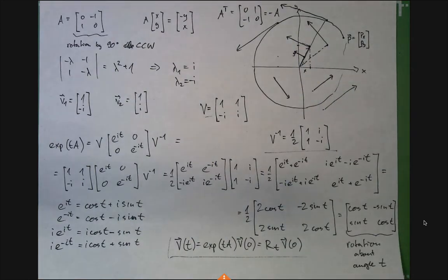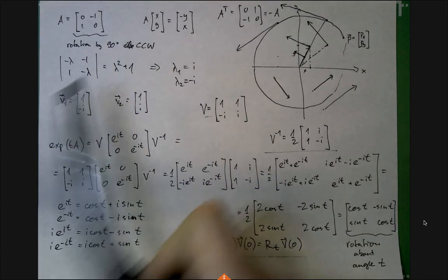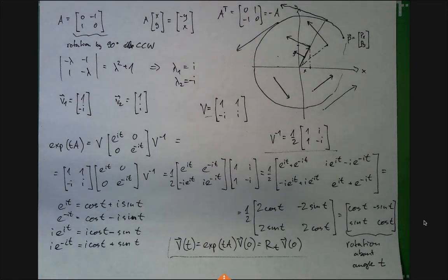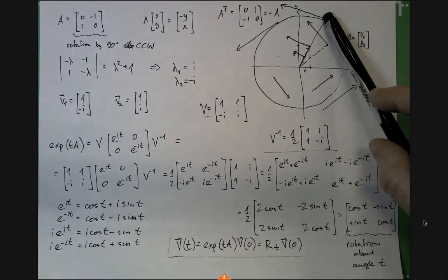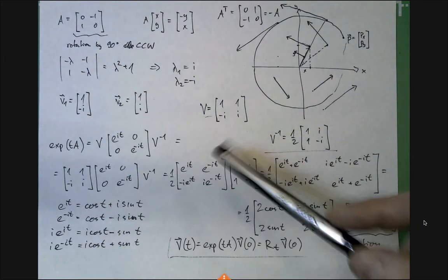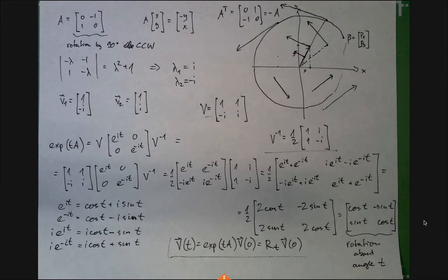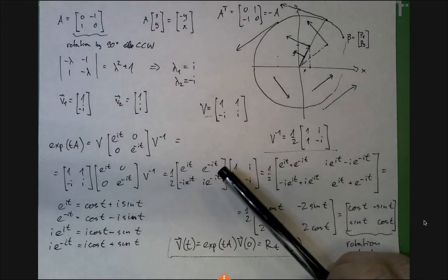So what we have just seen here is that anti-symmetric matrices are generators of rotations. Or you can also look at them as essentially linearized rotations, linearized in the sense that they give you the instantaneous velocity of a rotational motion, okay? So that's exactly what this does. If I have a point somewhere, what the matrix times X, or A times P, where my point is P, does is tell me the instantaneous velocity of the rotational motion. And if I solve the corresponding system of ODEs, you see that the exponential reduces exactly to a rotation matrix. So I think this is quite cool.